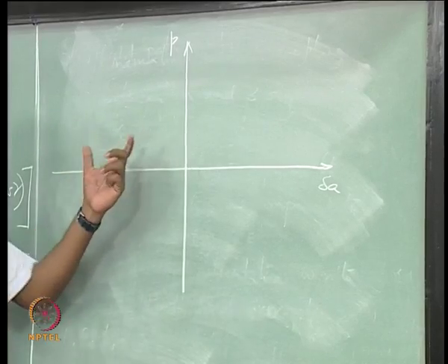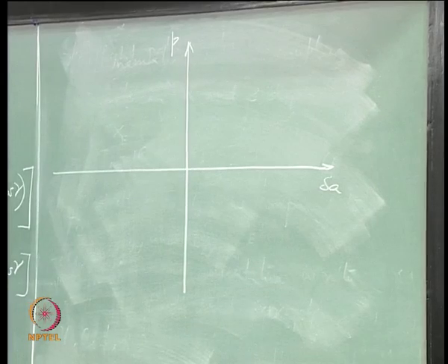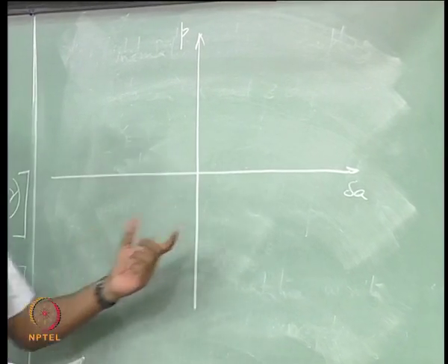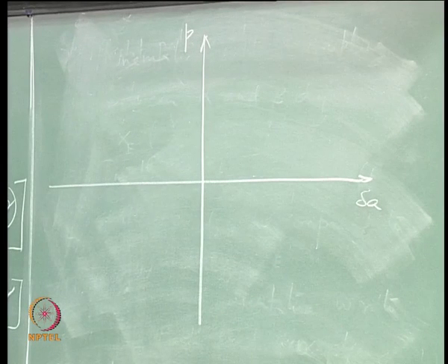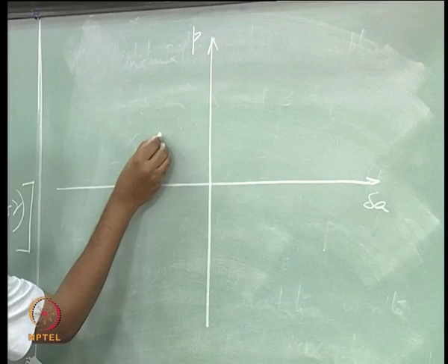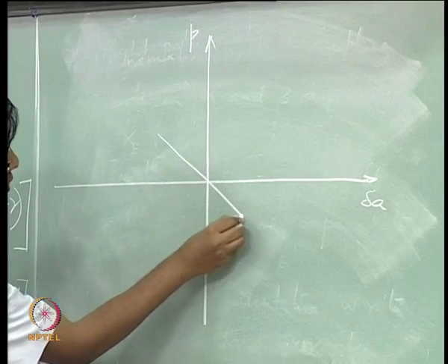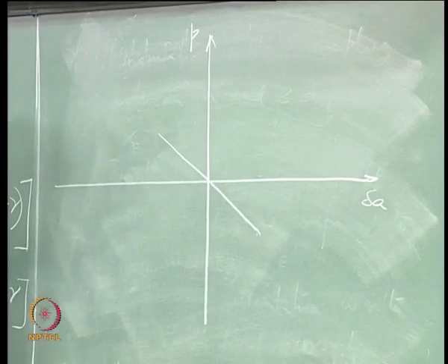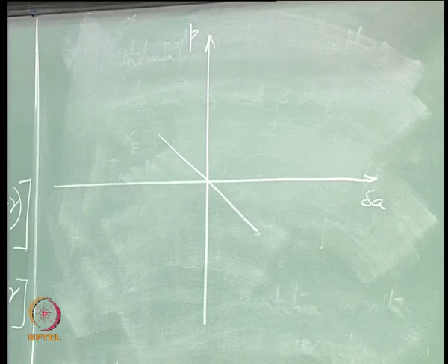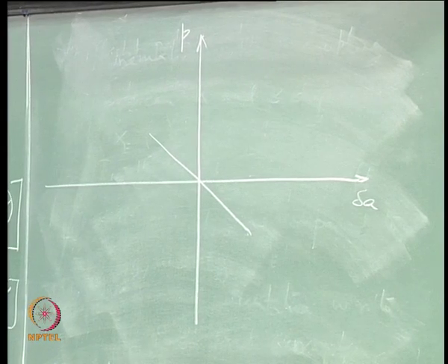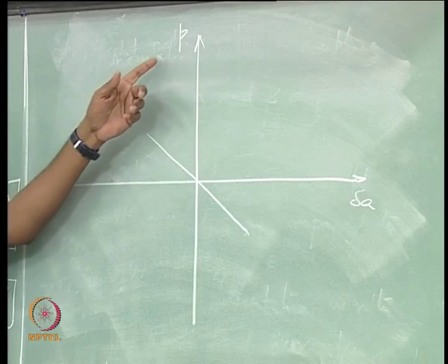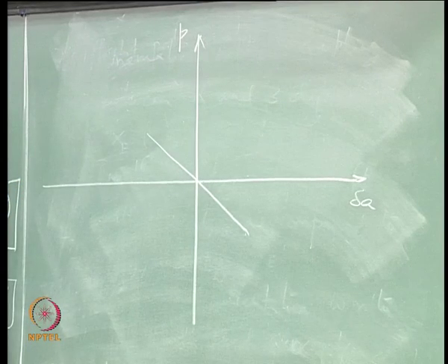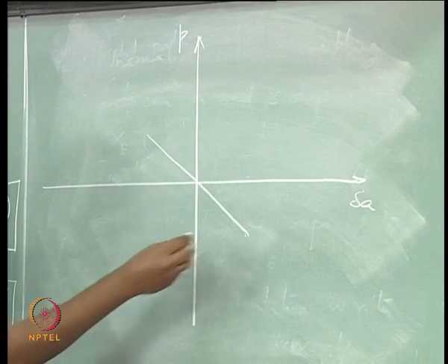And this is because of the inertia coupling term, right. So we are deflecting aileron and we are expecting some roll rate, and that is going to be linear up to some limiting value of aileron deflection, right. Not that you will keep getting this linear increase in roll rate when you are applying aileron for all values of aileron.